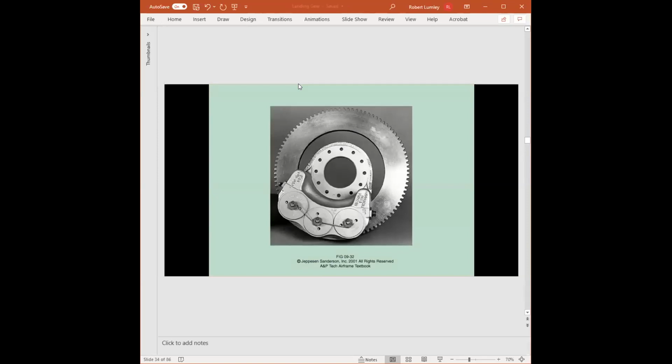Here again, we have a floating disc system. In this floating disc, yes, the notches have been replaced with a sawtooth design. So the rim actually has the sawtooth design also, where this is integrated into the rim. We can see where the fixed caliper is bolted to the landing gear. This one actually has 3 pistons, okay?